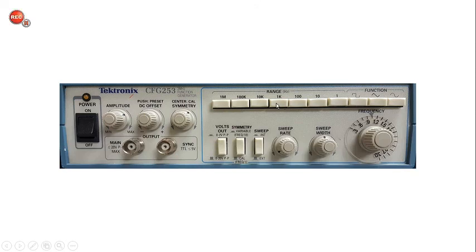We will pick a value that is generally close to the value that we're looking for. So we could get 3 kilohertz by pressing the 1K button and then turning this knob to 3.0. And so 3.0 times 1K is 3 kilohertz. And so that'll be roughly the frequency of the signal. We could also press the 10 kilohertz button and set the knob to 0.3, and 0.3 times 10 kilohertz again would be 3 kilohertz. So those are the two ways that we could set the frequency of the function generator.